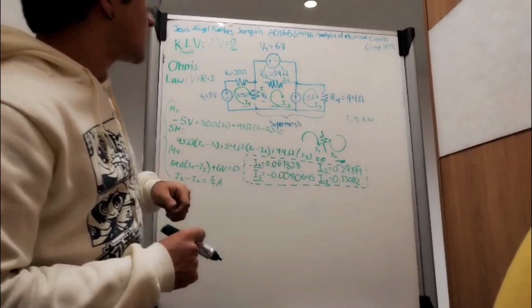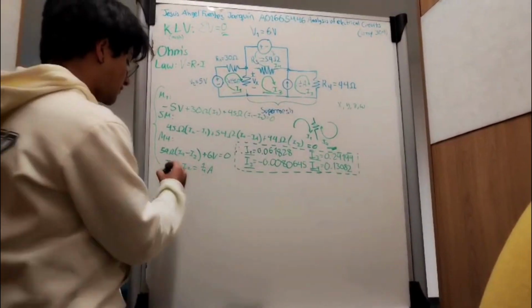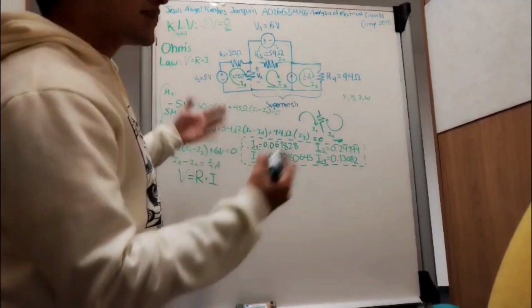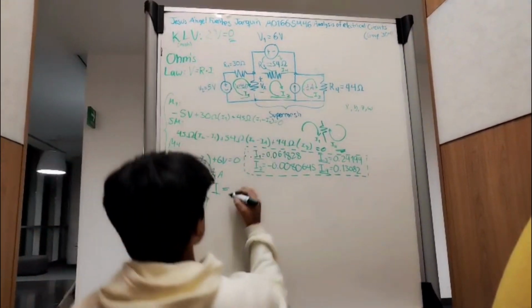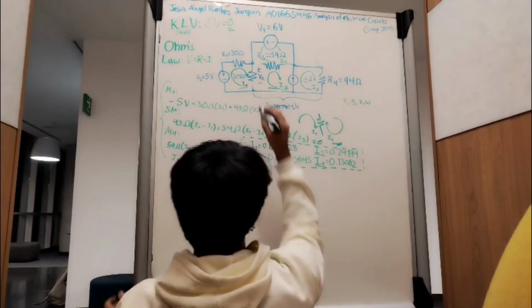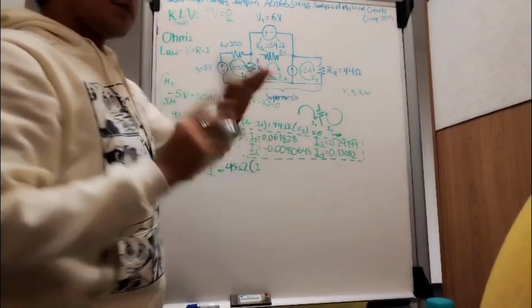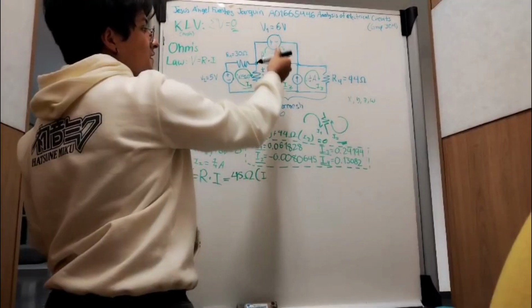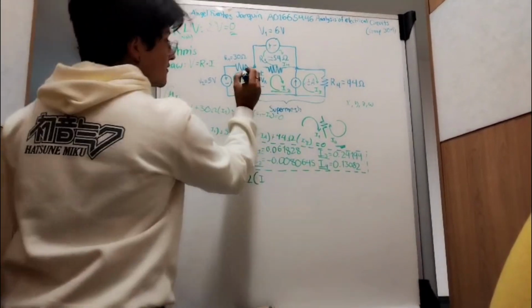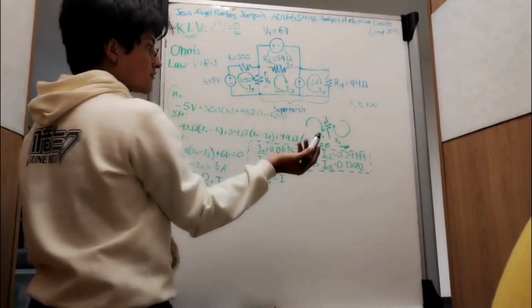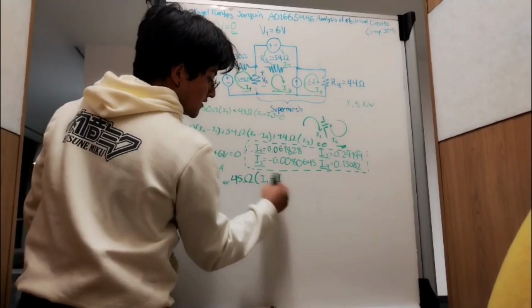So, the Vx is going to be solved through Ohm's law. In this case, Ohm's law states that voltage equals R times current. So, it's easy to know that we need to work with this current, that is 45 ohms times the currents that are dealing with the branch. So, here's the trick. In this case, we can see that the current, the loop, is behaving in this way. It enters the positive, it comes out negative. So this is going to be our positive. And in this case, the I2 comes in negative and comes out positive. So it is going to be stated as a negative sign.